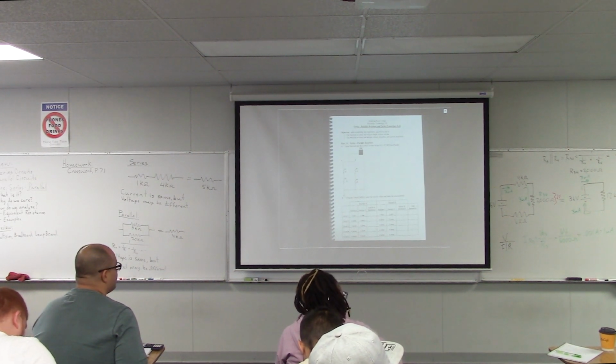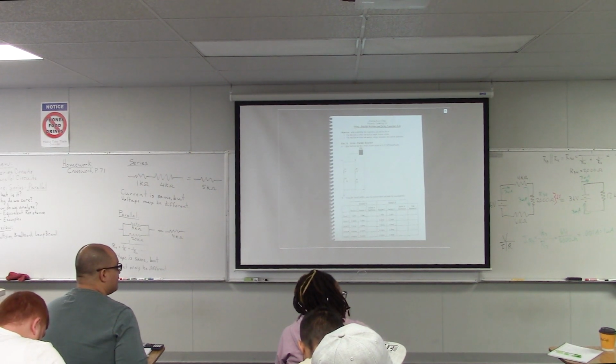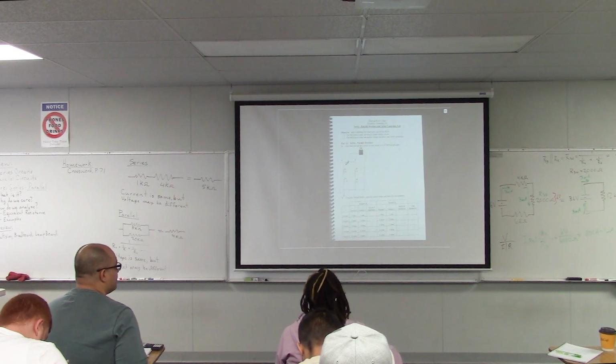Almost. So you take the resistance of one branch and you divide it by the number of branches. So it'd just be 1 ohm, because you have 2 ohms divided by 2 branches. That just gives you 1 ohm. So you would measure this using Multisim, and hopefully your total resistance would come out to be 1 ohm.